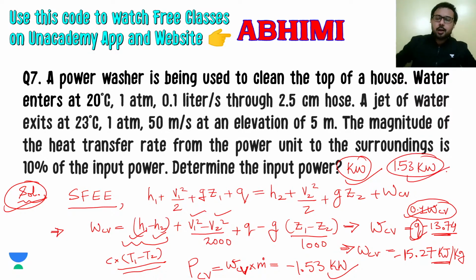So again, not a very hard question, but certain things you have to take care of: what values you have to put for water, and how you have to include this heat transfer, which is 10% of the input power, in your whole calculation. The final answer can be calculated as minus 1.53, but don't include the minus sign in your answer, because power in the control volume is not asked, input power is asked, so no need to add a minus sign.